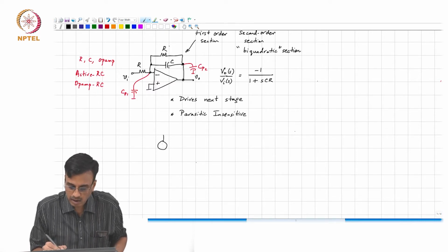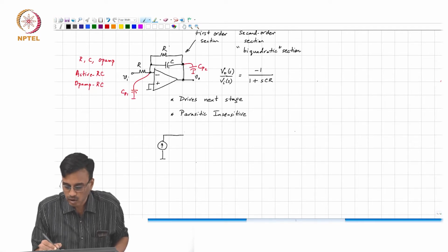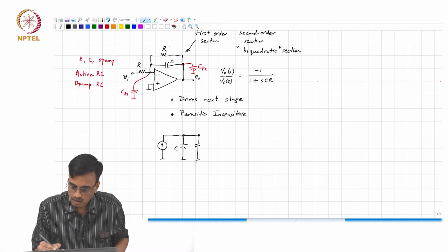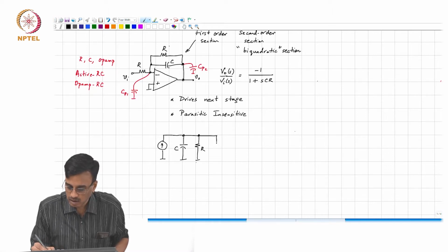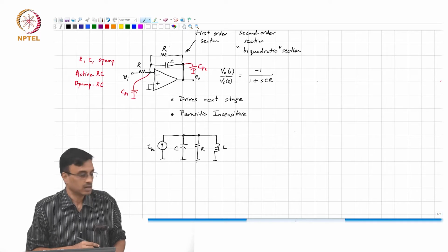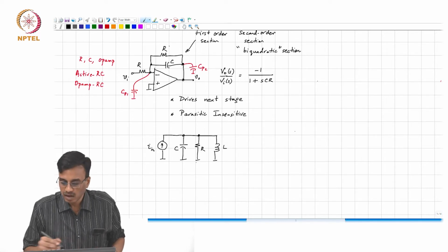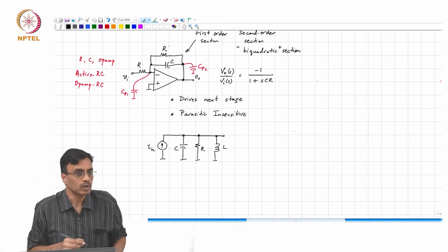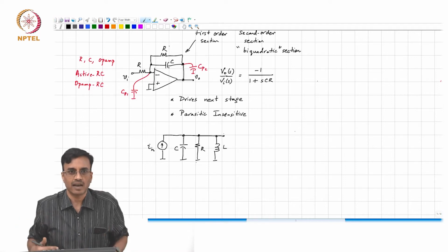And as we said yesterday, we can draw our inspiration from any number of second order filters that we already know. For example, this is a simple structure that we've seen in our earlier classes, right? The voltage output, as we discussed yesterday, is a band pass output. If you want a low pass output, what would you do? The inductor current has a low pass response.